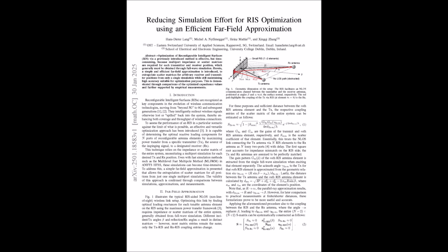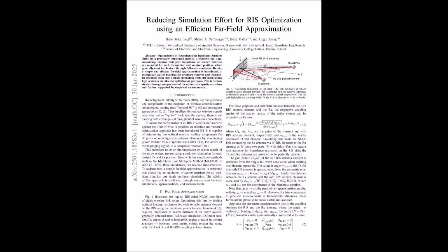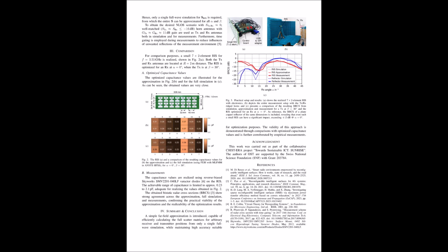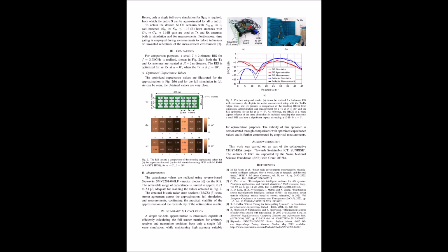Okay, so the phase shift basically tells us how much one wave is shifted relative to another. What does that have to do with the signal traveling from the transmitter to the RIS? As the signal travels that distance, d_TXm, its phase changes. This term in the equation is capturing that change in phase. And the reason this is important is that when the signal arrives at the RIS element, it might be slightly out of phase with signals arriving from other elements. Right. And depending on how these signals align, whether they are in phase or out of phase, they can either reinforce each other or cancel each other out, which can significantly impact the overall signal strength.